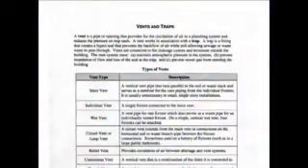Let's highlight right underneath the diagram. Drainage pipe may be any of the following. It can be cast iron, galvanized steel, galvanized wrought iron, lead, copper, or brass, ABS, PVC, or the last, in some ways most important, any other approved pipe. So these are the common materials, some of course more common than others, some hardly used at all, particularly brass because of its expense. Let's go on to the next page, page 26, vents and traps.